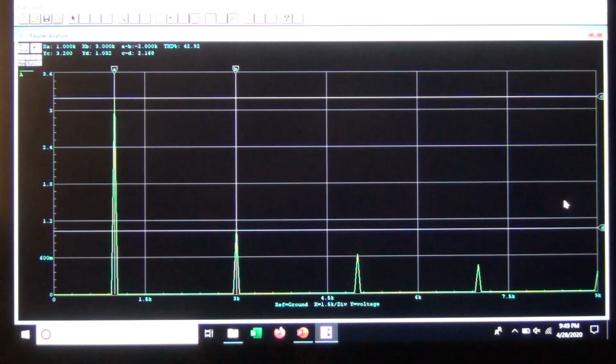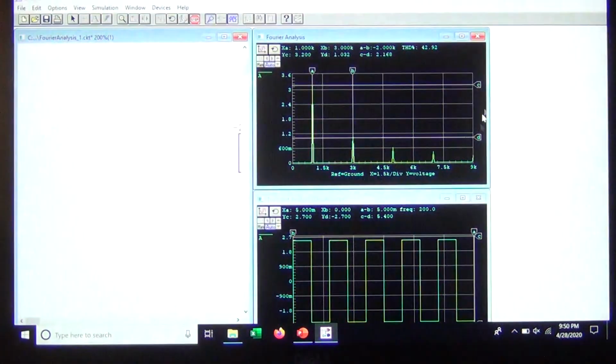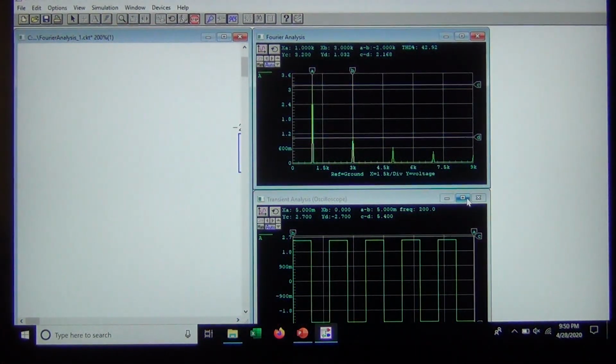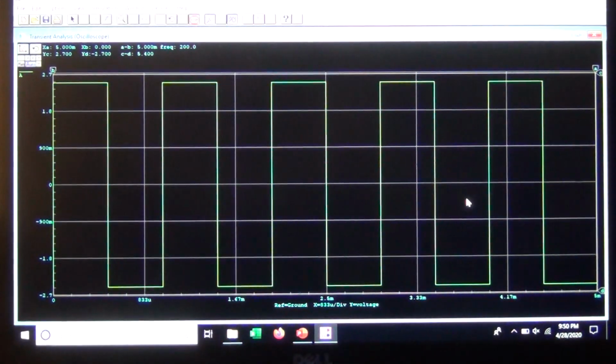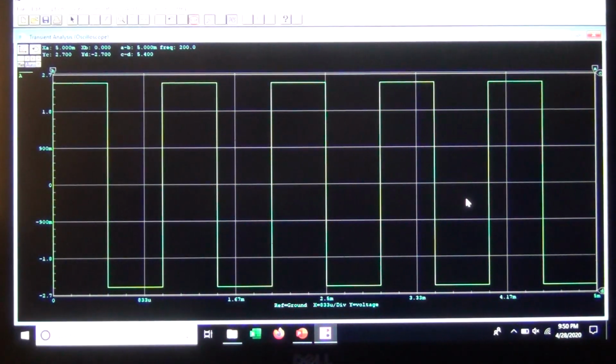It turns out that mathematically that's what the Fourier series would show, that a square wave consists of odd harmonics of the fundamental, and the amplitude goes down by 1 over n, which means their power would go down by 1 over n squared. You may have a problem wrapping your head around this, but sure enough, let me go back, here's the square wave, and we mentioned before that I could do this mechanically.